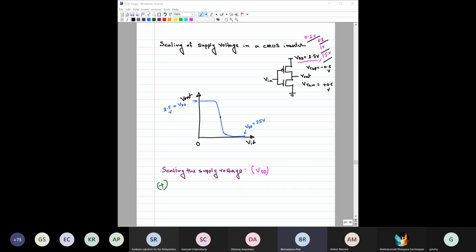Yes, sir. Yeah, thank you for answering. Could you please let me know your opinion? Sir, I think if we take it very low, like if it is less than 0.5 volt, then VGS will always be less than 0.5. In that case, the transistors will always remain off. So in that low voltage case, I think it won't work. Okay, so in that case you think the inverter will not work, right? Yes, sir. Otherwise, there will always be a cutoff region and a triode or saturation region.